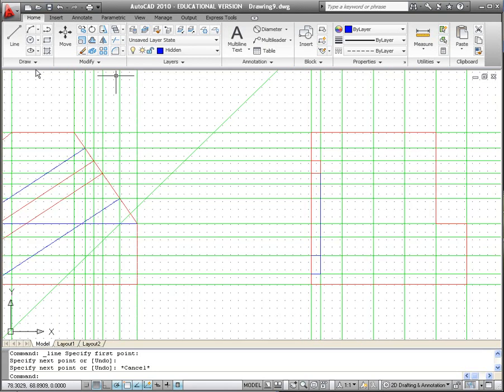Now the next one I'm going to do is another ellipse. I'm going to get a visible corner or line for the ellipse. Select ellipse, and then from my center point I'll come over here, so that's the center of my circle. That's my side, that's my top. So in this projection, it's kind of canted back from you a little bit, so it's narrower top to bottom.